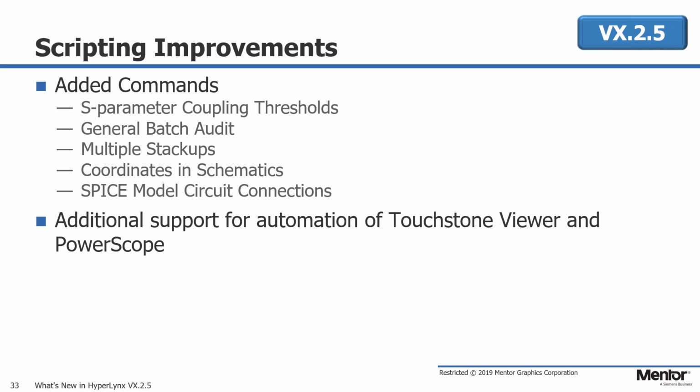run it again and come up with a final report of which nets have crosstalk issues based on both simulation and the HyperLynx DRC tool. And all that ran with scripting, so it turns into just a simple wizard type flow to go through and come up with those results. Anyway, so some advancements there.